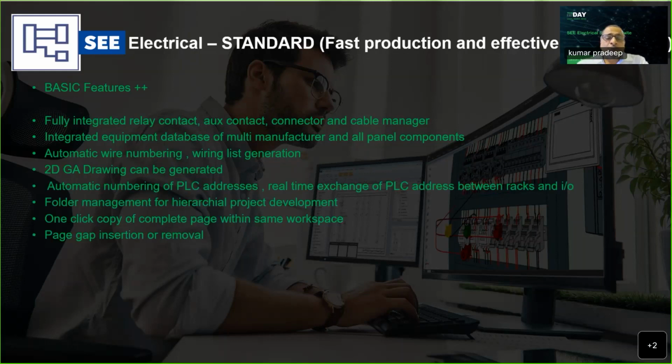When you are making panels with PLCs, it also has features of automatic numbering, taking input from the Excel if you already put it. You can have folder management, you can have hierarchical project development where you have the total project as one cover, then you have the sub projects in multiple folders and you can manage it. Then you have some features like one-click copy of one page. If you have created a page and you want to use the same page again in the project, you just select the total page and copy paste. You don't need to redraw everything. And if you want to have some page gap of insertion between two projects or in the same workspace, you can create that.